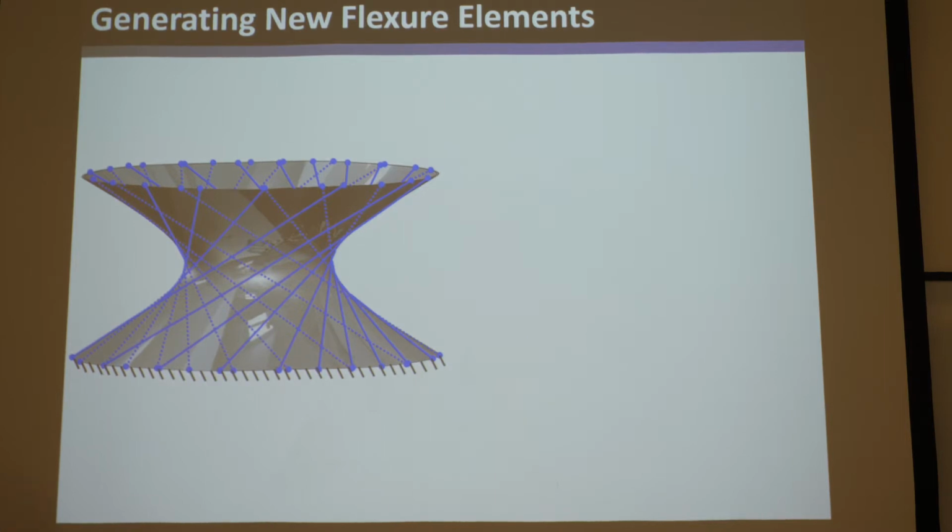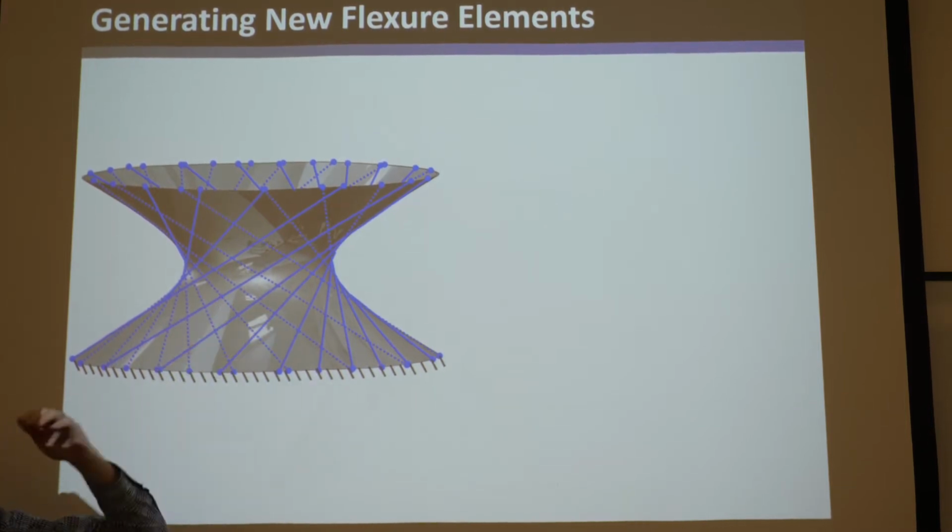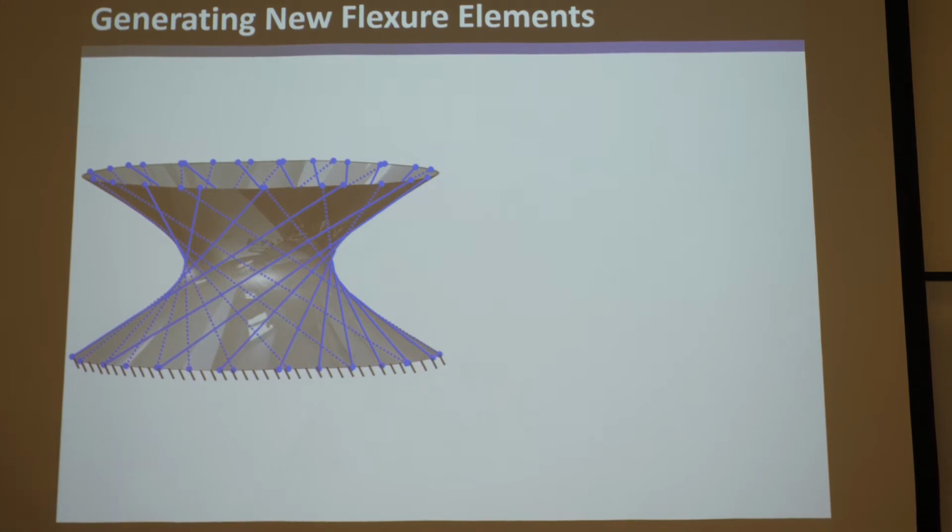They all can pass through. They can all satisfy those conditions. They directly connect the two bodies. They don't ever exit the geometry. And they can fill the entire thing going either way, either this ruling or that ruling of lines, right? So it's definitely a parallel element, but what is its order of constraint?